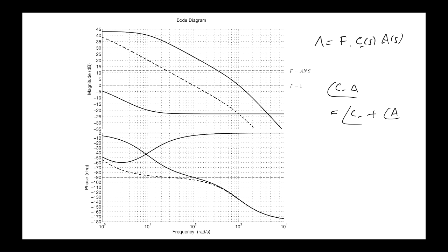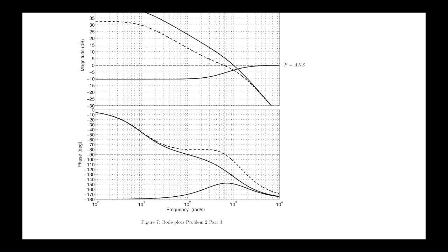So sure, we could leave f equals 1 and get the phase margin close to 90, 85, still no oscillations, but the crossover frequency will be 100, whereas with the lead compensator, the crossover frequency is 100, 200, 300, 400, 500, 600, 700.